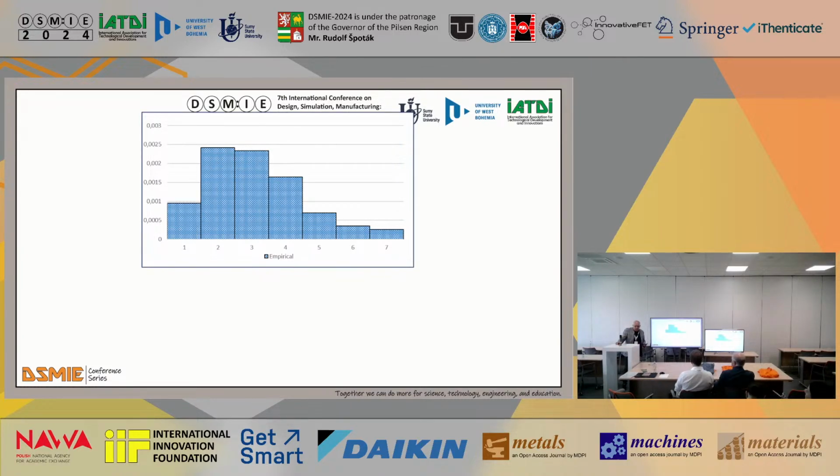So there are two problems in determining failure rate based on empirical data. Both of them are related to the fact that the theoretical function is continuous, while empirical data are presented in the form of intervals, as you see.